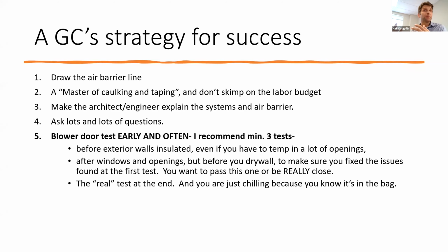And we didn't pass it, but we found a couple of really big leaks that would have been very hard to fix if we'd waited until those windows from Europe and those doors from Europe showed up. If we'd done the test then, I think we would have really been taking some things apart to go back and find the leaks. So asking how early could we do our first test helps find 1 or 2 big issues that you would never have thought of and catch them while everything's really easy to get to.